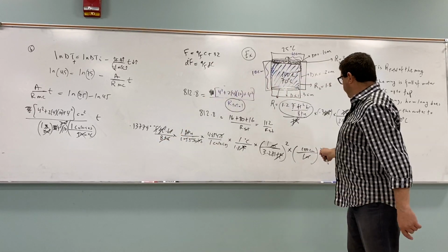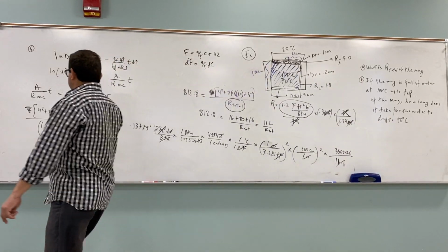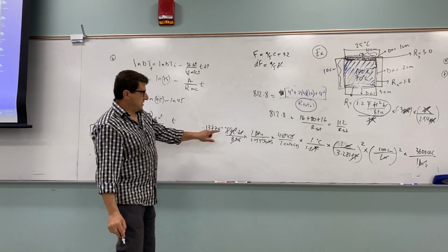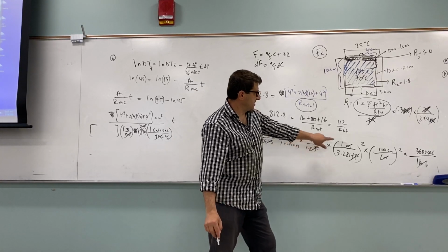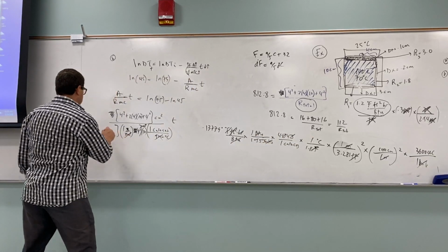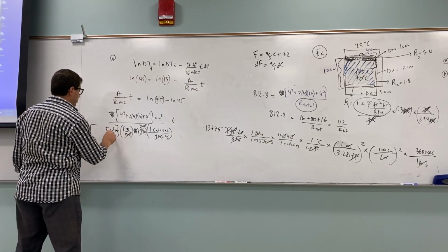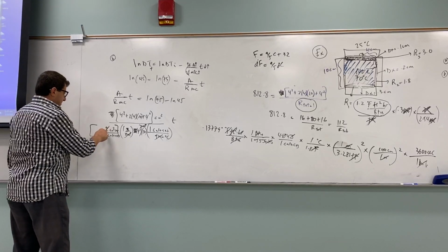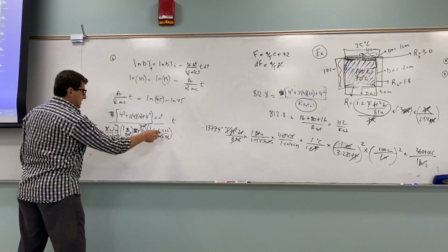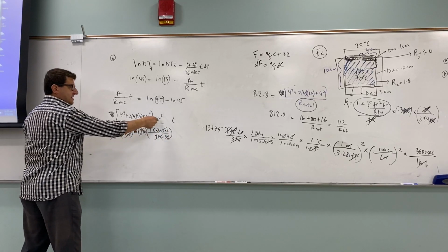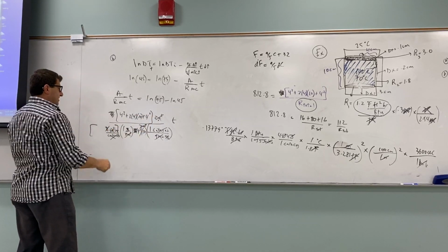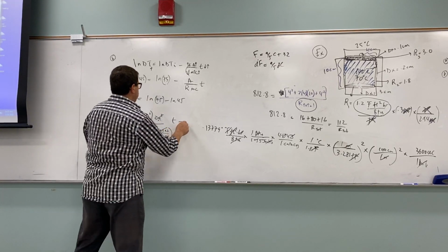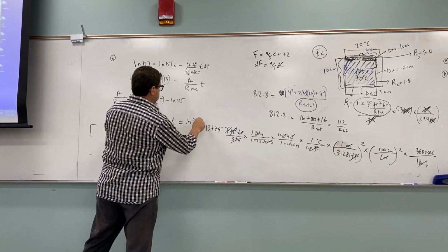So then, whatever number we get here, we're going to get some value of R, right? What are the units of that going to be? Celsius, centimeter squared, second, over calories, right? And then look at what's going to happen. Celsius cancels Celsius. Calories cancels calories. Centimeter squared cancels the top centimeter squared. And then seconds is going to be our answer for T, which is seconds. Then on the other side, you're going to have ln of the ratio of 75 over 45.